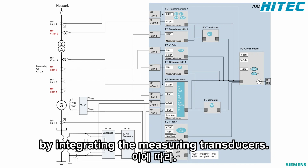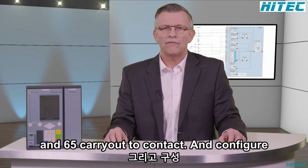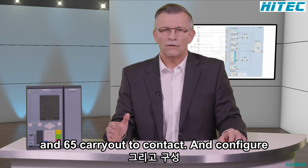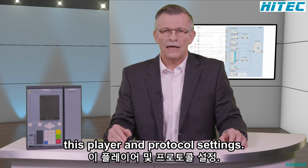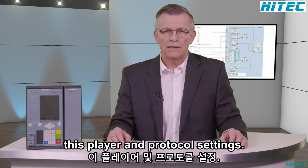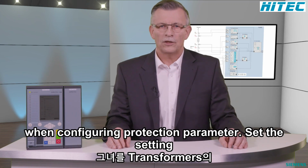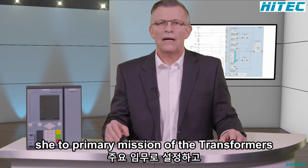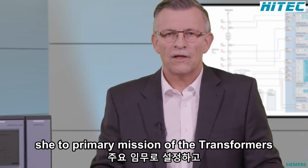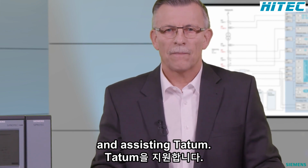integrating the measuring transducers. Now you can start with the implementation in DIGSI 5, carry out the configuration, the required routing, and configure the display and protocol settings. I recommend the following procedure when configuring protection parameters. Set the setting sheet to primary. Start with parameterization of the transformers under system data.